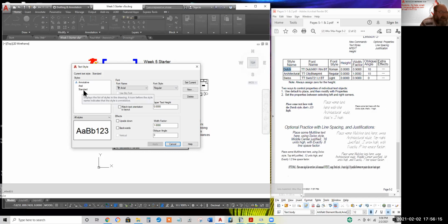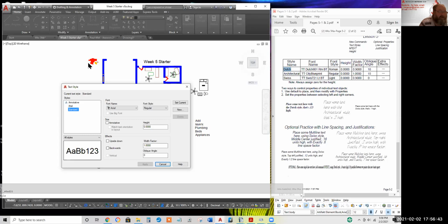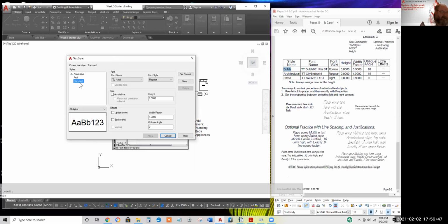Anyway, standard is, again, don't rename anything named standard. And I felt sure old AutoCADs would allow you to, I'm sorry, don't modify anything named standard. You used to be able to rename standard, and I'd name it junk and then import a pure standard from another drawing, much like we brought this chicken scratch from the other drawing, because that'll redeem myself if I accidentally butcher the standard text styles. But playing with it this afternoon doesn't allow me to rename it anymore. So deal with it. Anyway, select standard, keep it pure, cannot be renamed. Okay. In time you'll learn what it is, and you'll know what to change of it. So leave it pure so it can be a template or a baseline.